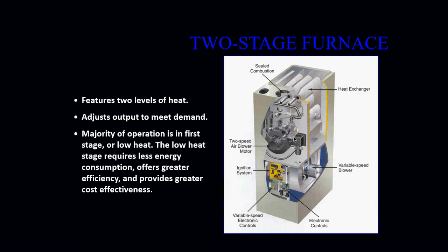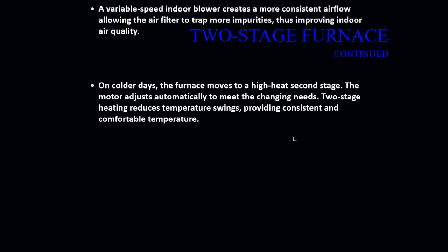Okay, 2-stage furnaces, they feature 2 levels of heat. Okay, they can consist of a modulating gas valve, which will ramp up and ramp down based off of the demand inside the house. Okay, they adjust the output based off of the demand. Majority of the operation is in the first stage, or what we consider low fire or low heat. The low heat stage requires less energy consumption and offers greater efficiency and provides greater cost effectiveness.